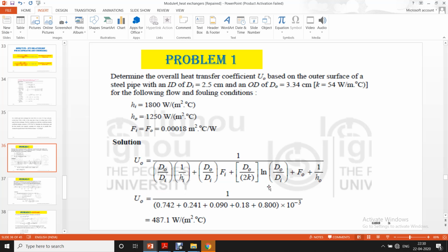So this overall heat transfer coefficient value is to be used to calculate the heat exchange in the heat exchanger. This particular problem is just a demonstration of how to calculate the overall heat transfer coefficient if it's not given in the problem. In certain questions, even Hi and H out values will not be given directly. In those cases, from the Reynolds number and the Prandtl number values and the flow configuration, we are required to calculate the Hi and H out, and then from the Hi and H out values we need to calculate Ui or U out. There are questions being asked in university examinations also, which require the calculation of Hi, H out, etc., and from that we need to calculate U, and after that we need to calculate the total heat transfer or any other missing parameter like area or length of the heat exchanger.